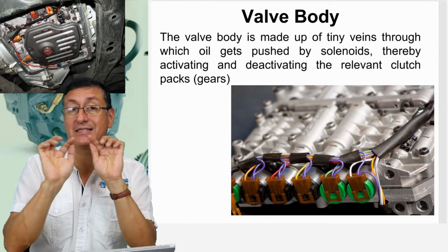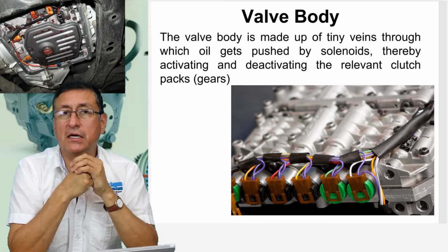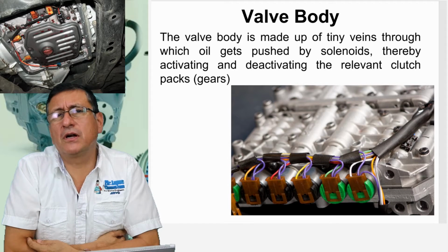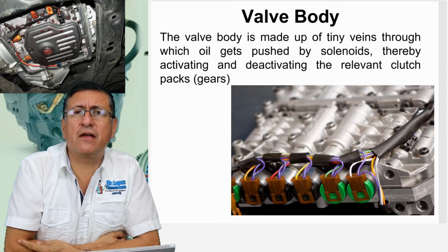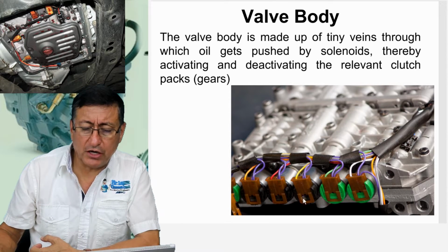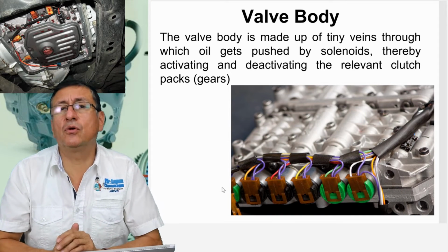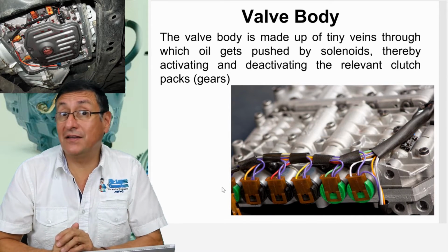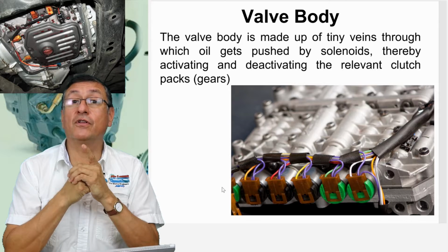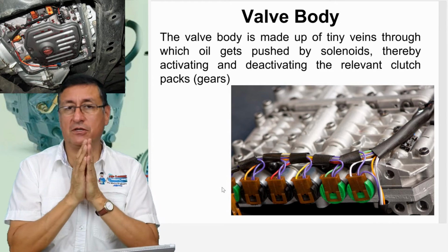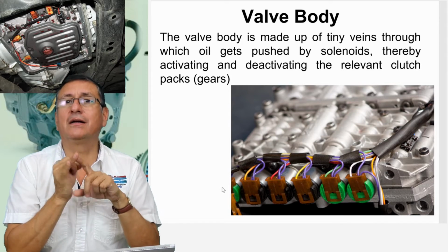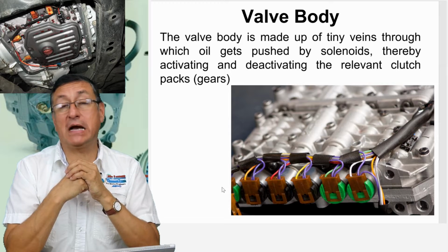Yes, on the side of the valve body are located the solenoids. There are solenoids for forward, for reverse, for first gear, for second gear, for overdrive. For each movement, you have one of those solenoids, and those solenoids are activated from the computer. The computer receives the signal from the harness of the engine and the transmission, and according to the RPMs and the load, each sensor is activated. This is magic.